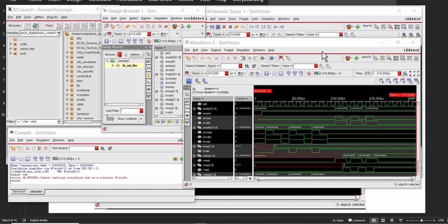To start with, we begin with our presentation and check how many commands there are for compile, elaborate and simulation, what the formats are, and how we can do these things on the terminal. More importantly, we can go with the GUI also, but I am trying to show the process of the general company standards, where they make some TCL files or makefiles through which they compile and simulate. So we start with that.